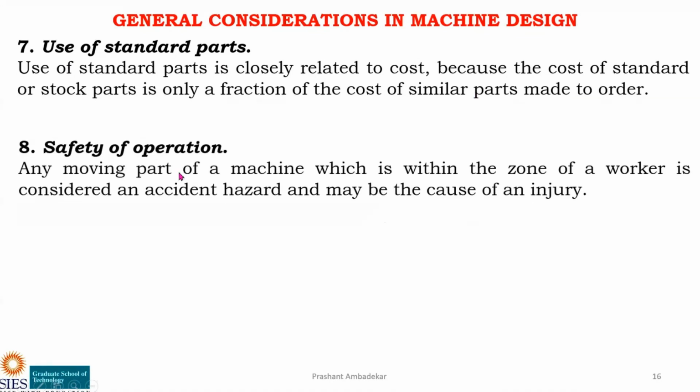Then safety of operation. This also we have covered. Any moving part of the machine which is within the zone of the operator should be covered, so that there is no injury to the operator who is operating the machine, and it will reduce the chances of any accident. So the safety of the operator should be seen first whenever a product is to be designed.